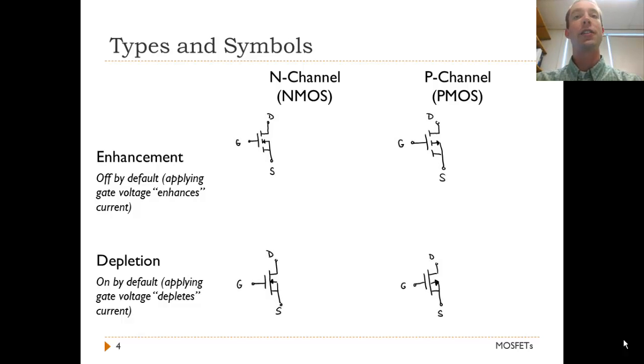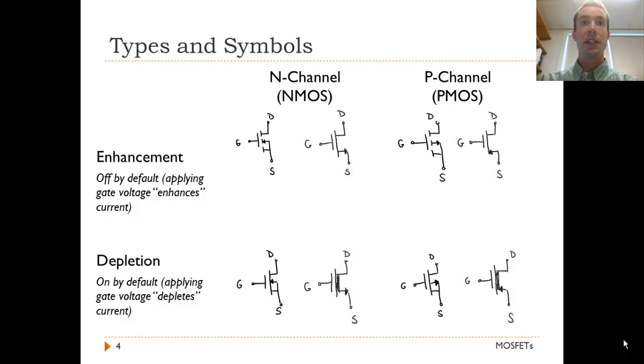All four transistor types have a number of similar but slightly different symbols used to indicate the transistor. In this first set, the arrow points from the P-type material to the N-type material in the device and can be used to determine P from N-type devices. In the second set, which we will primarily use, the arrow points in the typical direction of current flow under normal usage.